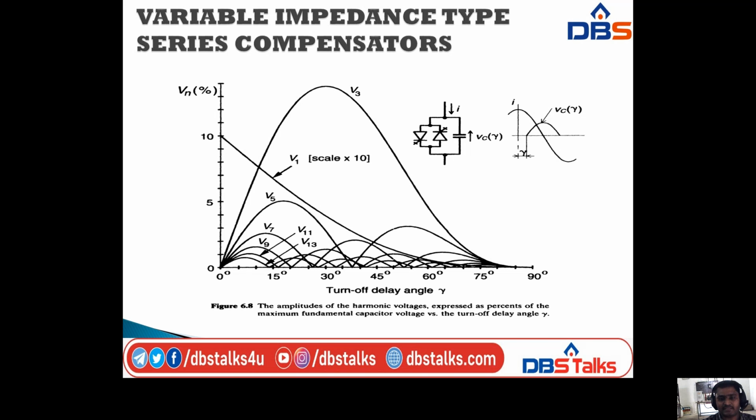This is the circuit representation. Here we are taking the thyristor valve in parallel with the capacitor. Here we have line current I, then the thyristor valve, that is the switch, then the voltage across the capacitor, that is Vc of gamma, and we have the waveforms like this, I versus Vc. So this is the explanation for that one.